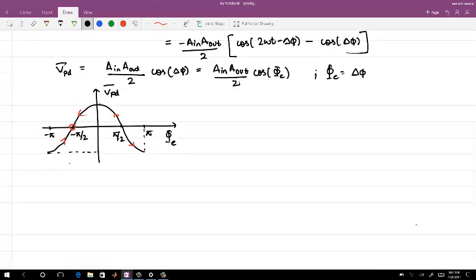Okay, so now this is just the phase error input output characteristic, and can you just say at which of these, if the two frequencies are the same, where will it lock to? If this is a phase locked loop, if the two frequencies are the same, it should lock to a zero phase error. Okay, and you are seeing there are two zero phase error points. One is minus pi by 2 and the other is plus pi by 2. So which one will it lock to? Pardon? Minus pi by 2. This is as per the stable thing that you keep. If any delta changes happen, you again come back to the null.